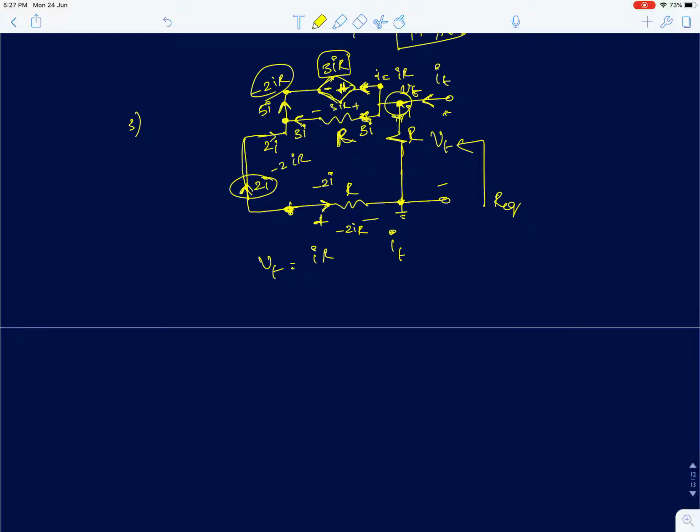So now we'll go back to the input point. Through the resistor you have a current I flowing downward, and into the other resistor you have a current of 3I flowing, and from the dependent source you have a current 5I entering. So what will be the current here? The terminal current will be I leaving this node.